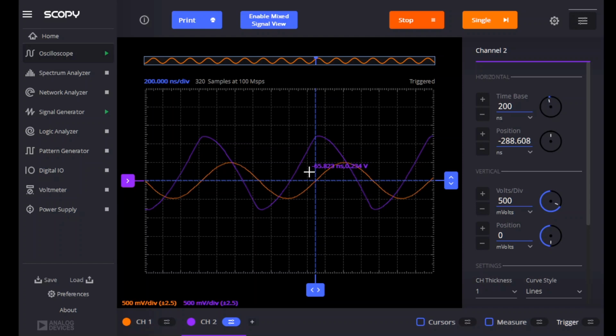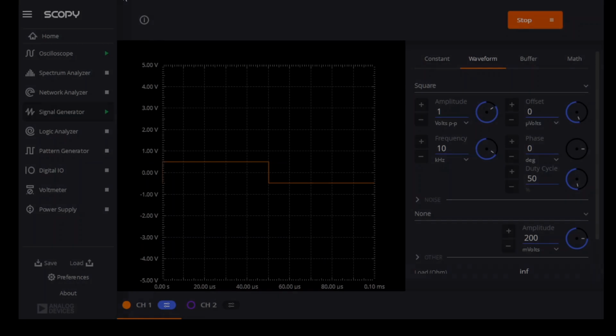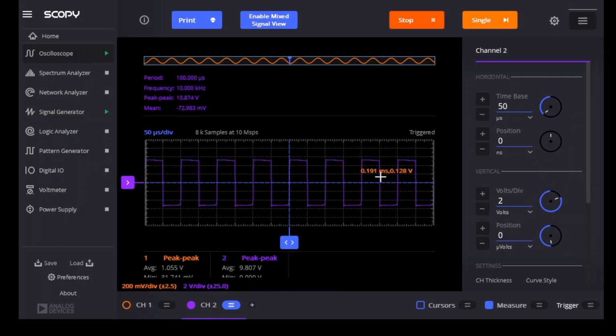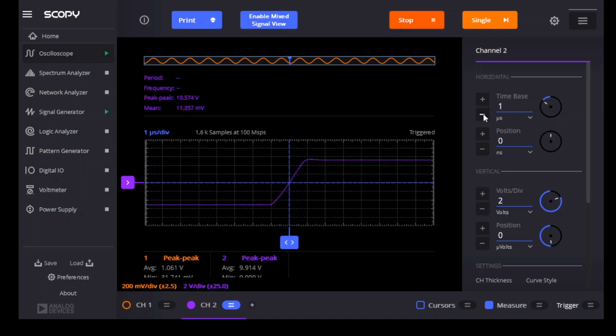So to measure this, we can switch to a square wave. I reconfigured off camera to save time. The signal generator is now generating a 1 volt peak to peak square wave at 10 kilohertz. And the oscilloscope is just showing the output. It's also triggering from the output signal. The input's turned off, so we don't need to look at it. And so we can see that we're seeing an output square wave, but the slew rate determines how fast the square wave can rise. So if we zoom in here, we'll see that rise time is definitely finite.